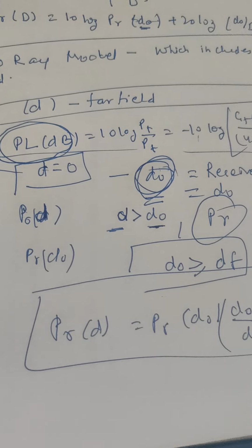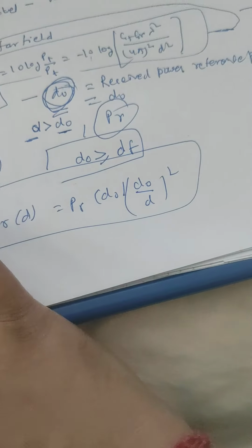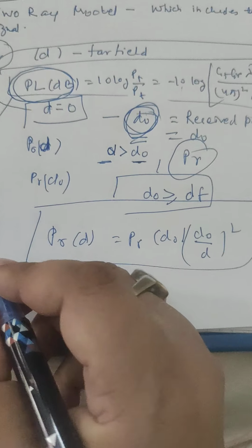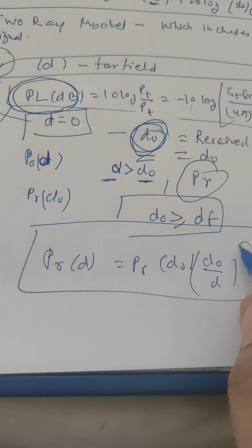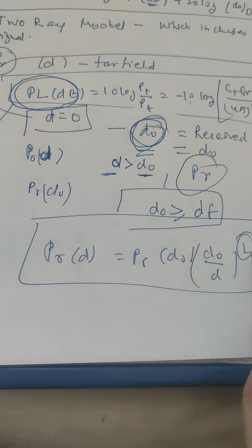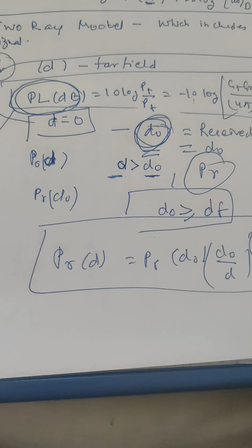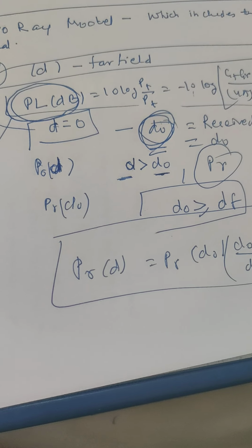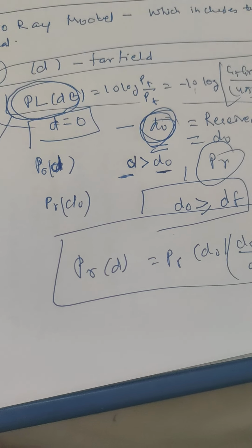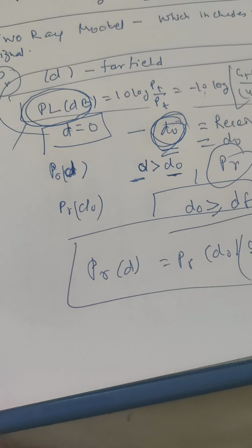In mobile systems, it is not uncommon to find the received power change over many orders of magnitude over several square kilometers, because it is the square of the distance, and because of the large dynamic range of received power level, it is expressed in dBm or dBW.